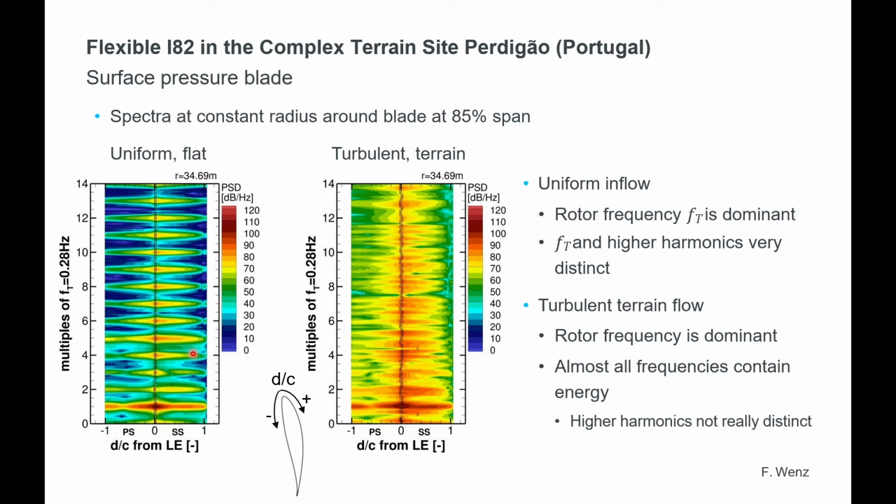But this time you see turbulence increases significantly the amplitude for the signal emitted from the blade. You see the amplitude is higher. We see only red colors. We see a smearing. We see a more broadband response. And that was quite interesting because atmospheric turbulence changes the situation for the low frequency noise emission significantly.